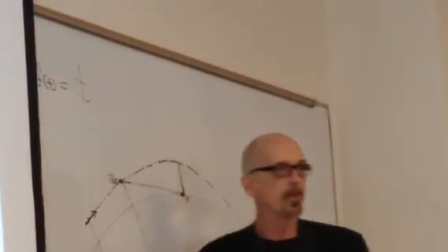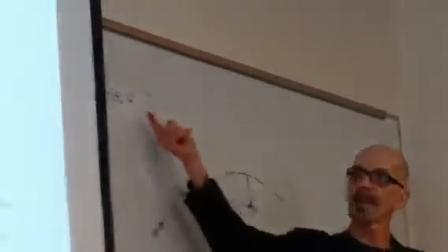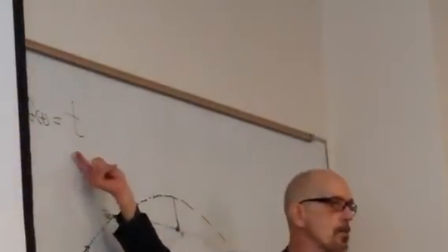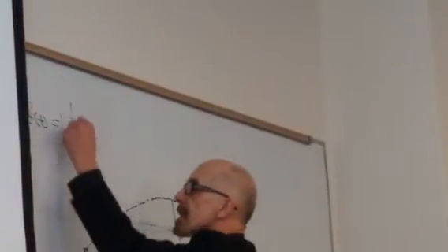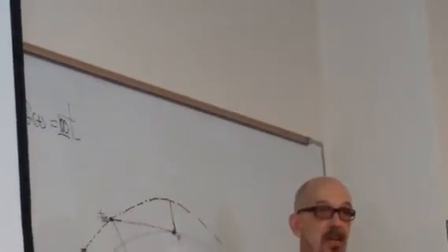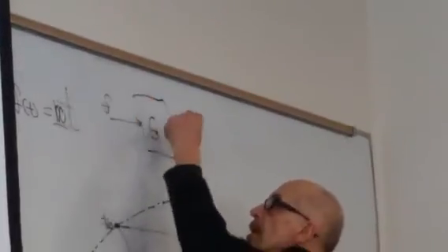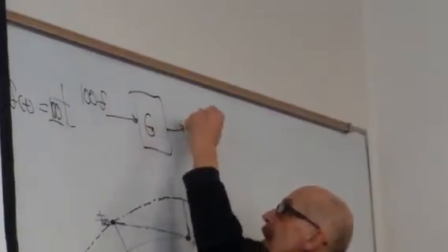So if I specify this much steady state error for a unit ramp, and you give me a ramp that's this, I'm going to have 100 times the steady state error, because it scales. The magnitude of the input scales to the output. Right? If you take a block diagram, G, and you put in F, you get Y. If you put in 100 F, you get 100 Y.